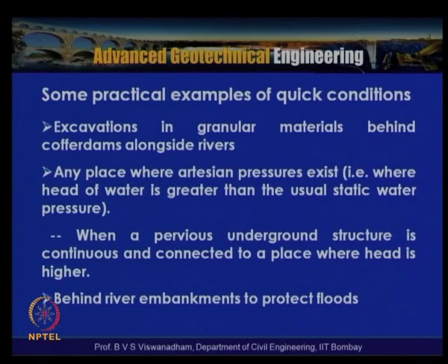So, this phenomenon, we have also said that it occurs when there is a higher head of water in the soil beneath, either because of a water source or because of some pervious layer beneath an impervious layer. In that situation artesian conditions may exist, and if an excavation is made in such soils, they can be subjected to a phenomenon called boiling condition, and particularly it can lead to a failure. This happens when a pervious underground structure is continuous and connected to a place where the head is higher.